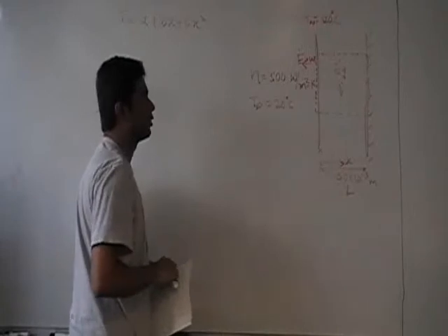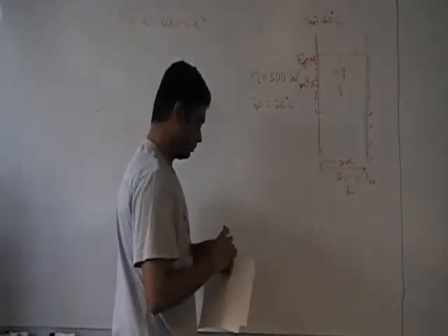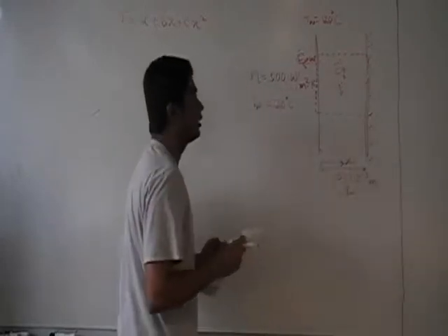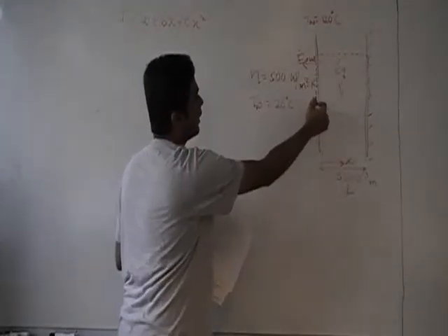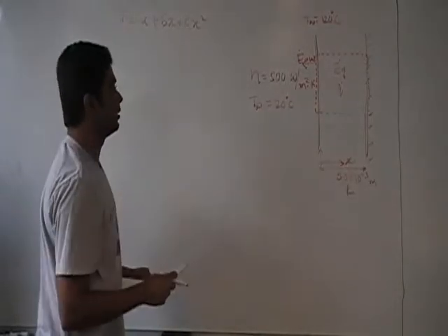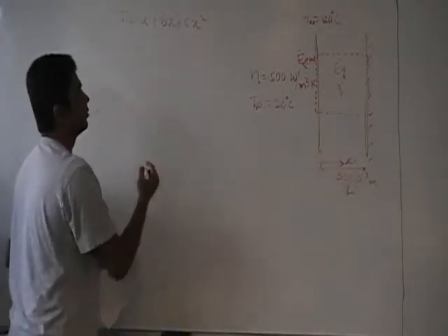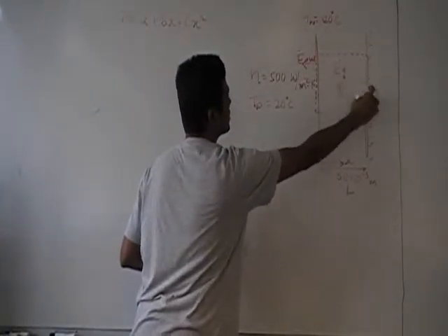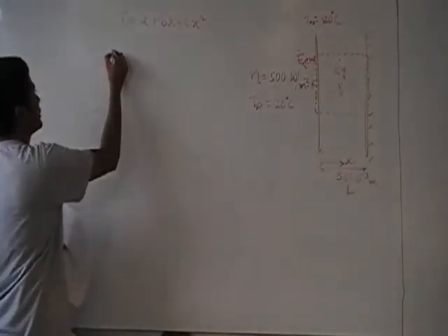So now let's look at the boundary conditions. We have one boundary condition here at the adiabatic wall. We have one here at the wall facing, which is convecting out to the environment there. That one is known from the temperature here. The other one is known from the slope here. So writing them down, the first boundary condition is